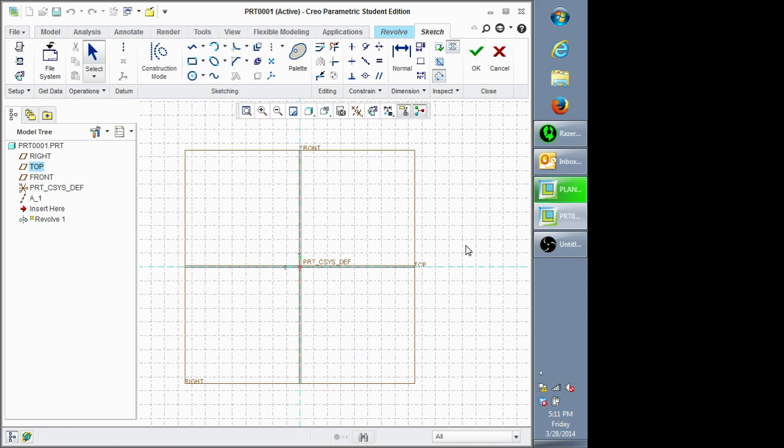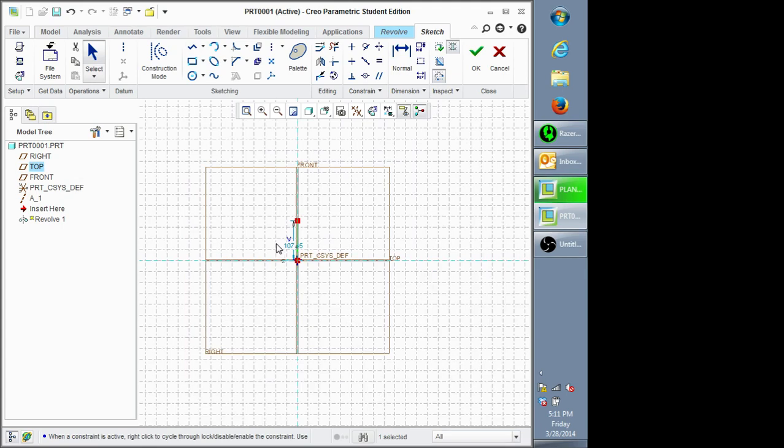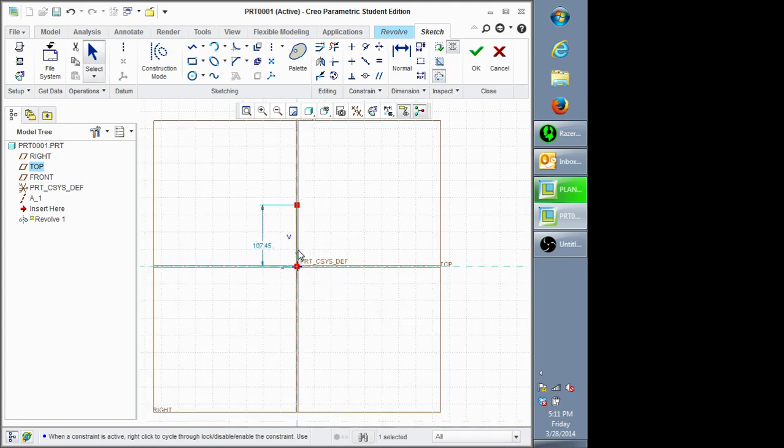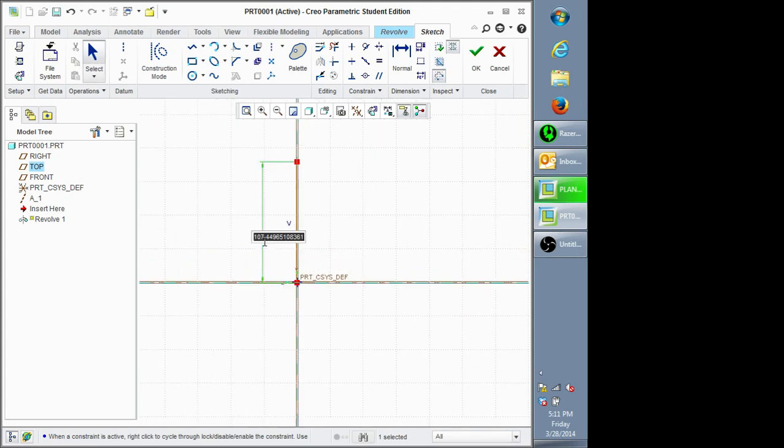So now it's all set up. Let's make this datum plane right here at the back edge of the propeller nose. So we can go in. Let's create this line right here. So go up. We're actually going to make this thing really big. In this dimension that pops up, double click it, and set it to 50.